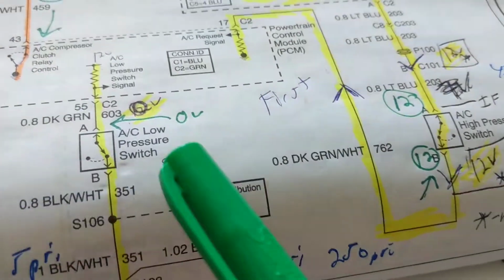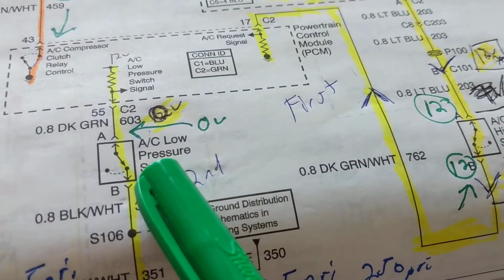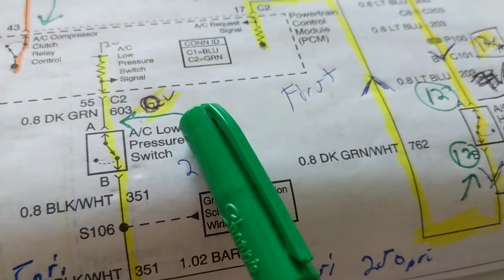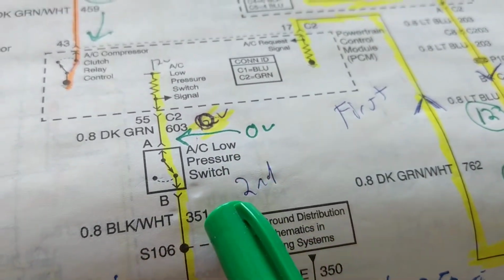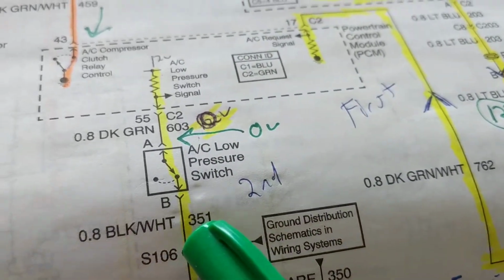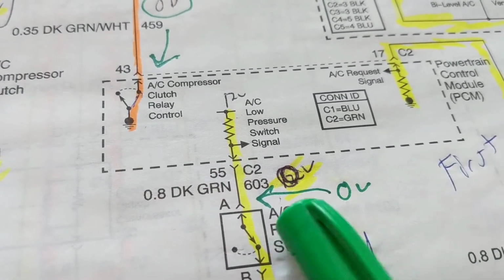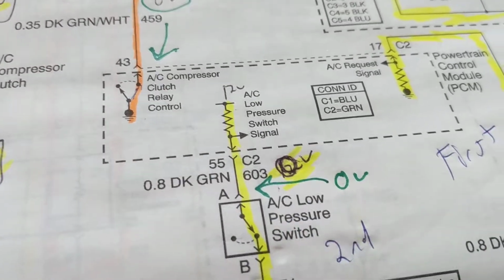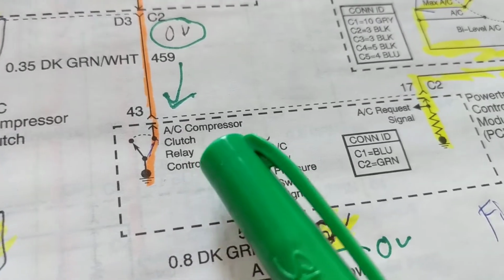So in other words, these are not tripped. This didn't trip, like a circuit breaker. This didn't trip. That's good. The computer says, fine. That's great. High pressure is good. It's safe. Low pressure is also safe because this switch is closed, the protection switch. Computer says, okay, those protection devices are closed. That means the pressure is correct. That means now I can activate the clutch.